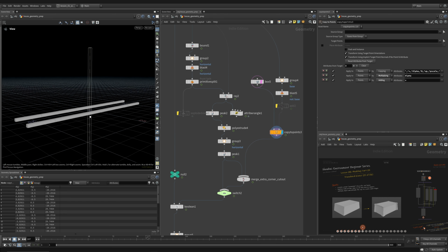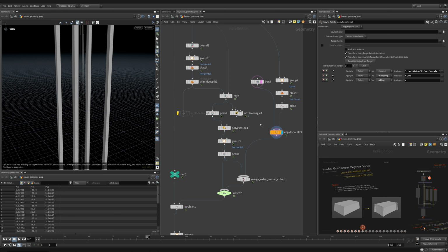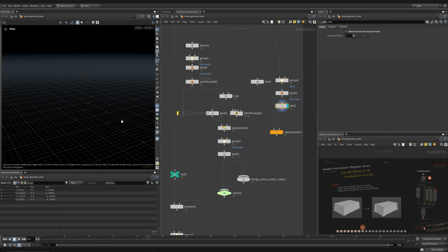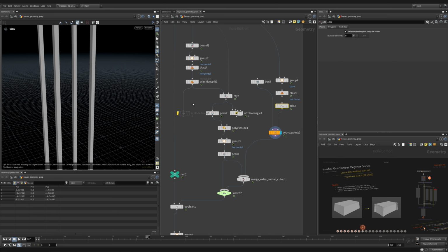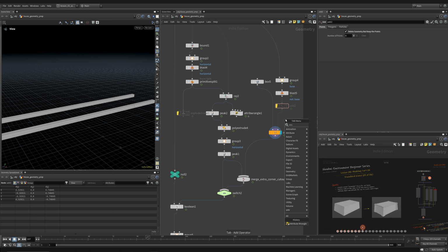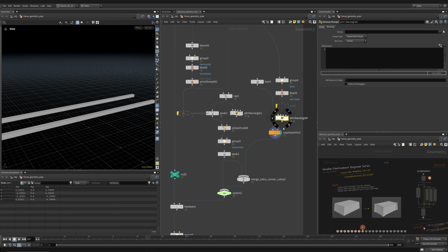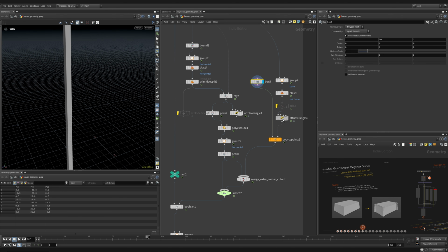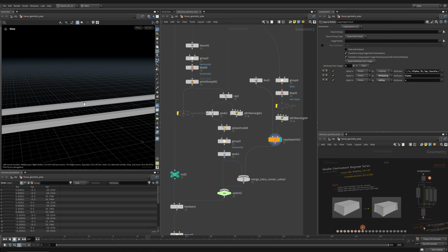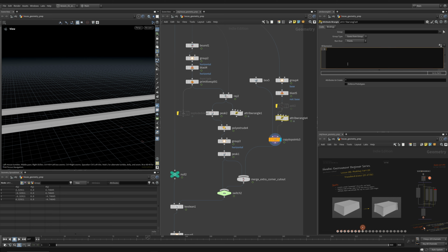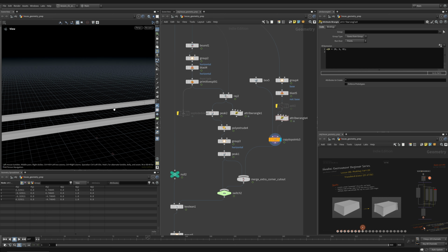The way I could fix this, actually what's going on here, this add is removing these points, and it looks like Houdini is then recomputing the normals internally to give me the correct orientation that I'm expecting. If for some reason I didn't want this add, what I can do is fix this, and the way I can fix that is by setting this normal. Let's see if we can guess ahead. So Houdini, when it does copy to points, it instances the positive Z direction, so it looks like this direction, along the normal of our object. So if I set this normal, v at n equals 0, 1, 0, so the positive direction, it'll do nothing because that's what Houdini's already doing here.